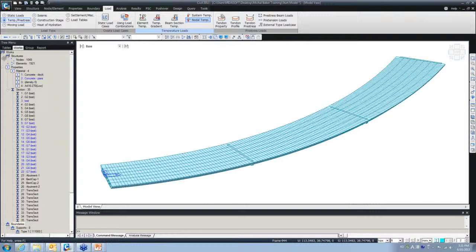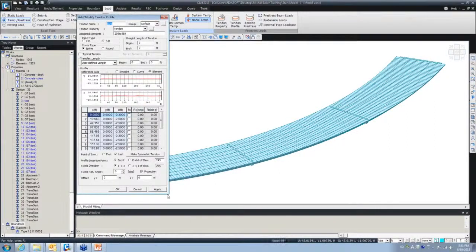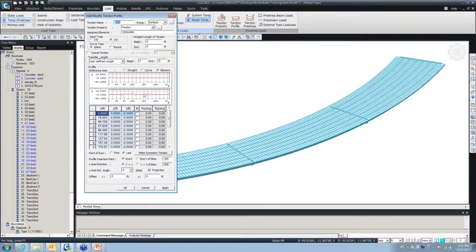All right. So this will be the tendon profile that I want to define. You can see the tendon profile is very small because we have a 300 feet long bridge, so you can't see these changes that much, but when I create it, you can see them better. But you can get some idea about how it's going to look. On the first abutment, it's going to be somewhat above the neutral axis, then it goes down, and again on the first support goes up, down, so you can see that it's following the bending moment diagrams, and we're going to define it that way.